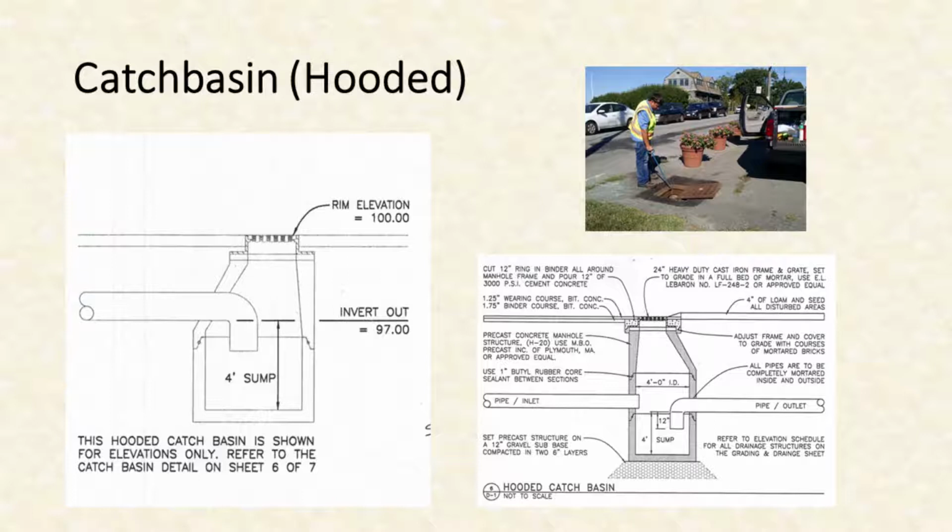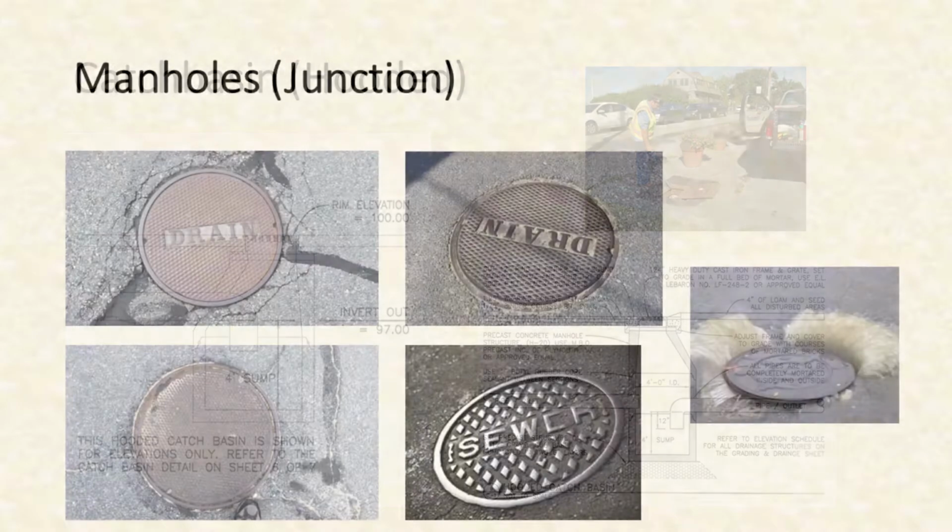The typical catch basin is constructed of concrete or brick and contains water and debris like leaf litter and sand at the bottom. That area that collects the debris is called the sump and may have standing water at times. When the sump fills with water, there's an outlet pipe to drain the structure. The illustration shown has an outlet pipe with a downward-facing elbow to reduce floating debris and oils from exiting the basin. Many of the newer or refurbished catch basins have this hooded structure, but older structures typically have a simple exit pipe. This exit pipe usually connects to another catch basin or a manhole structure.